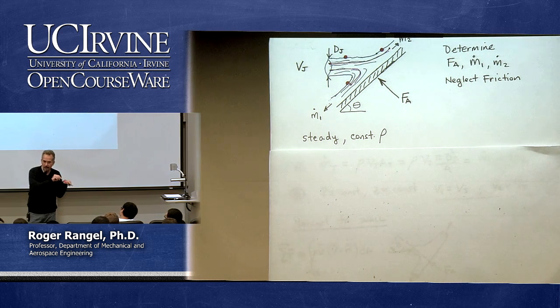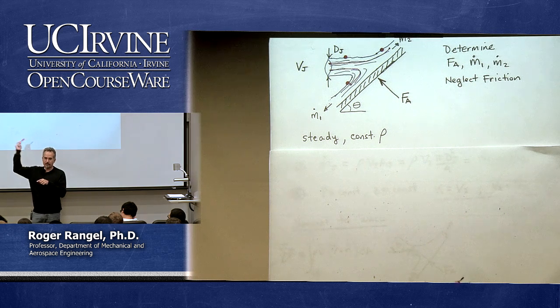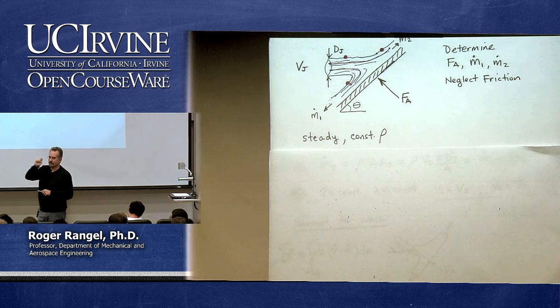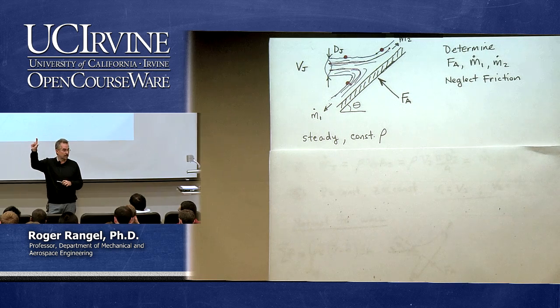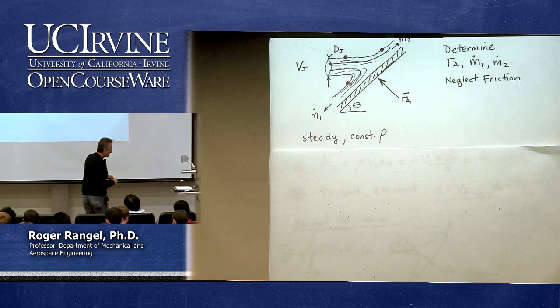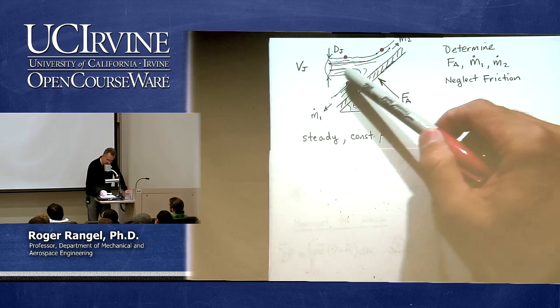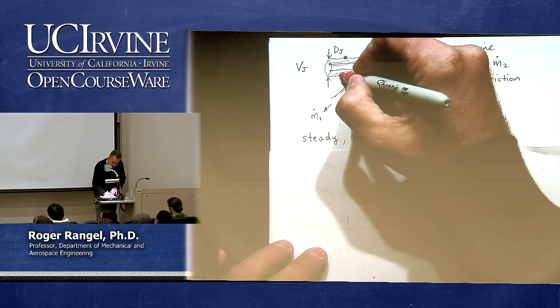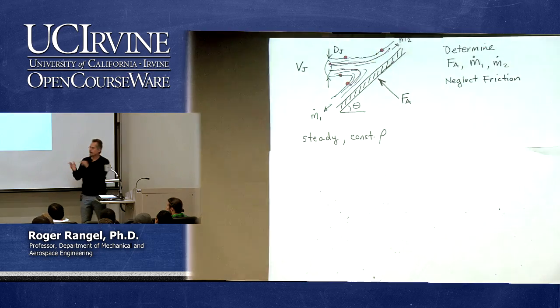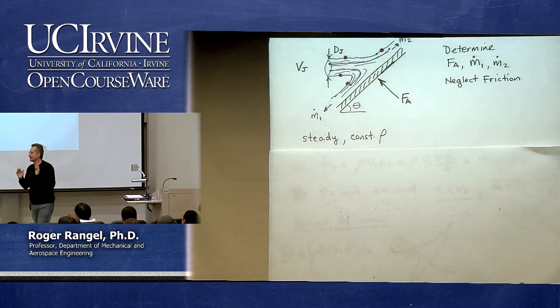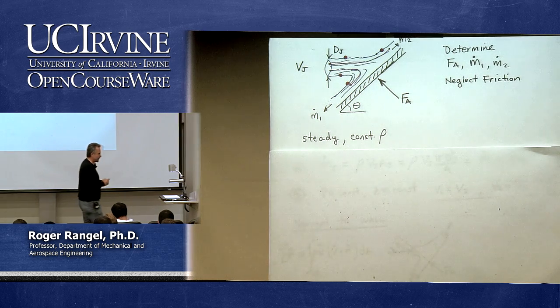Steady is an assumption that goes into the Bernoulli equation, and it's also an assumption that we made to solve the problem. The velocity would be the same at those two red dots. Look at the Bernoulli equation with the assumptions that we have just made. The velocity is then the same here as it is here, and therefore is the same here as it is there. I follow two different streamlines, of course, to get to the two places. So convince yourself that the velocity would be the same from Bernoulli's equation.